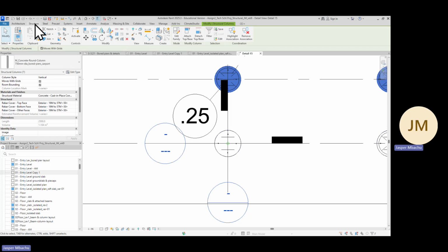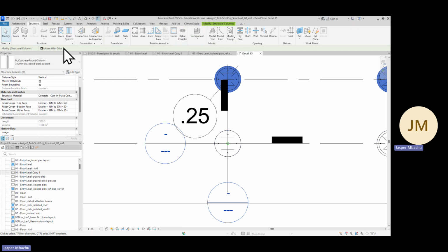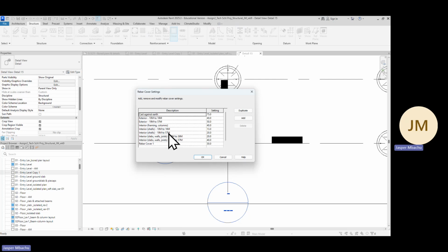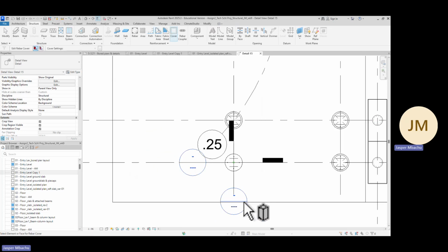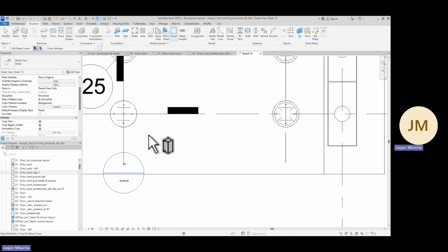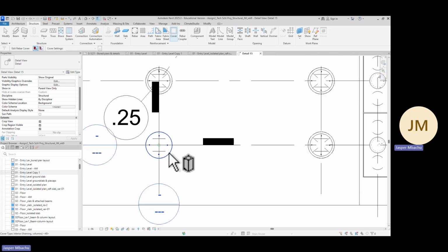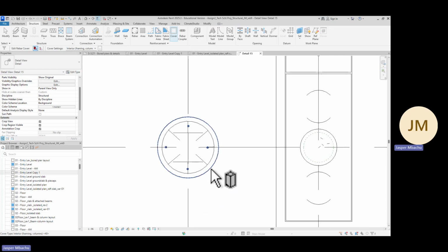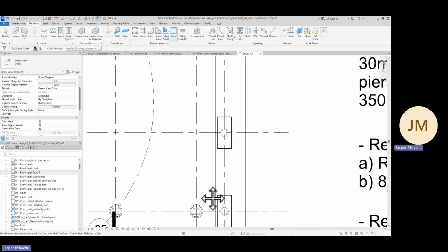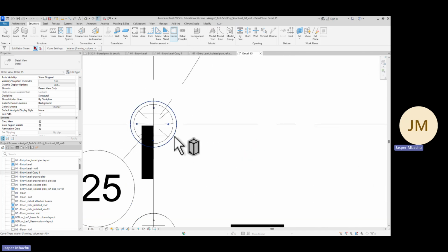And then we can go to structure and we will go to cover. And when we go to the cover settings, we have selected the 50 cover setting. Now, we still need to go individually. Before I thought because all of them are selected, they should all have the same cover. So this is picking a 50 cover. So you have to go individually, click each one separately, and the other one to click, until you select the 7 of them.